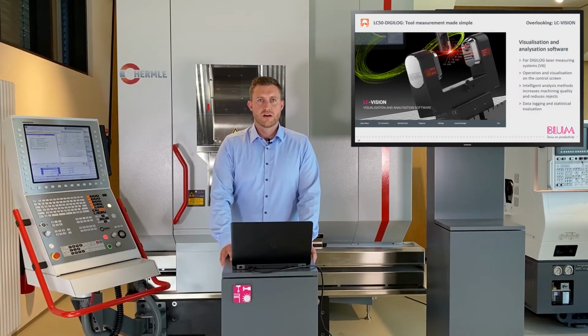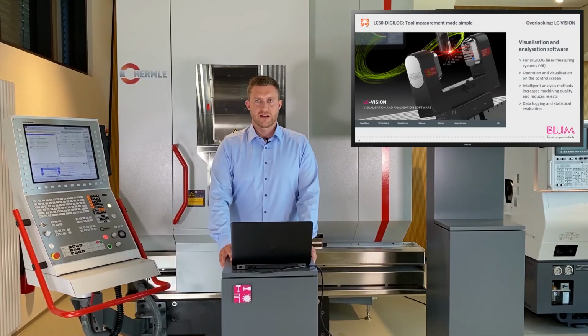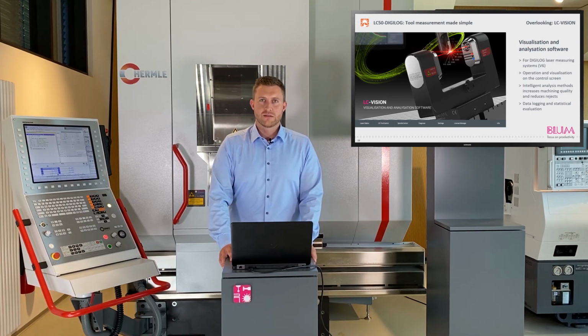The software uses the generated measured values to perform a quick optical analysis of the quality of the tool and the motor spindle. The stars of the show here are the intelligent analysis methods for enhancing the quality of machining. For example, if the laser measuring system detects wear, you can then generate application-specific data directly to correct the tool parameters, which can then be automatically included in the cutting process.